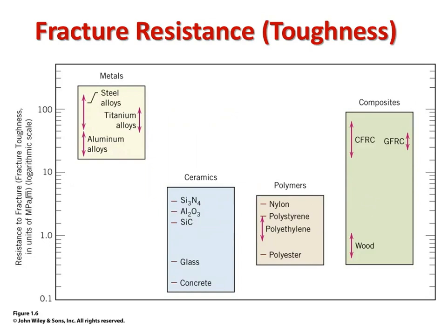Okay, fracture toughness. Energy per unit volume that a material can absorb. And this is what will give us our crack stopping capabilities, thermal shock, prevent us from catastrophically failing in service. Metals are another winner. This is another way that they pay for their very high density. They're very fracture tough, again coming from their delocalized electrons. Here's where you can see ceramics really failing. Ha, pun intended. Hopefully not, because we'll design them correctly.